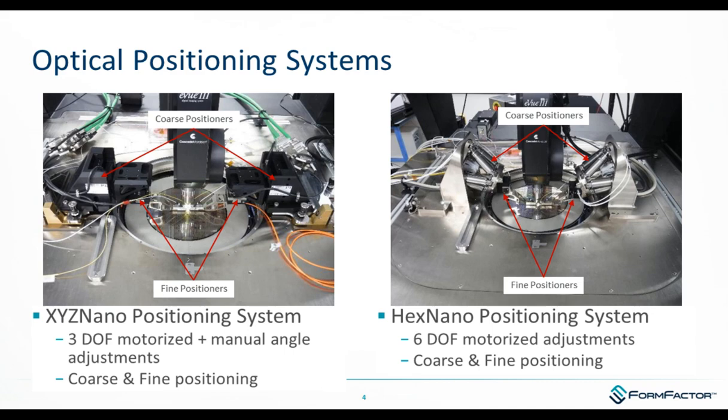Riding on the coarse positioner is the nanocube, or the fine positioner, which has 100 micron of motion, but with very fast servo motion to perform the optical scans. And then on the end of the nanocube, we mount the fiber holder and the fiber itself, and also the Z displacement sensor.